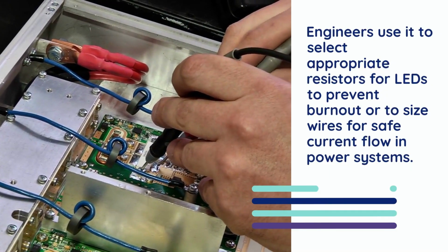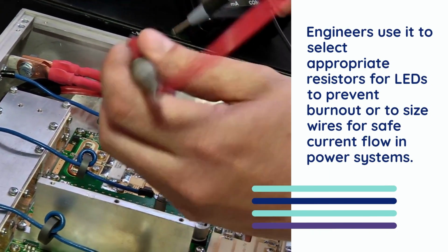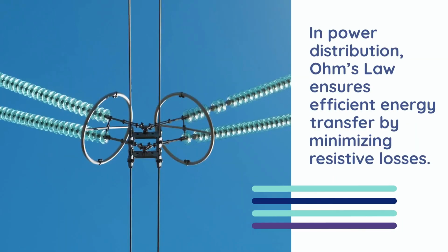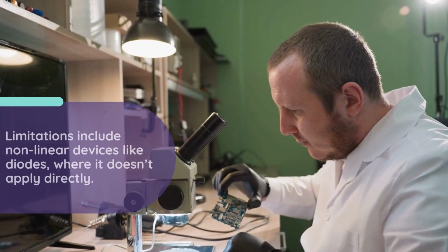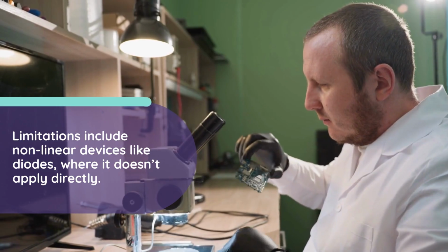Engineers use it to select appropriate resistors for LEDs to prevent burnout or to size wires for safe current flow in power systems. It's critical in troubleshooting, like identifying faulty components by measuring unexpected voltage drops. In power distribution, Ohm's law ensures efficient energy transfer by minimizing resistive losses. Limitations include nonlinear devices like diodes, where it doesn't apply directly.